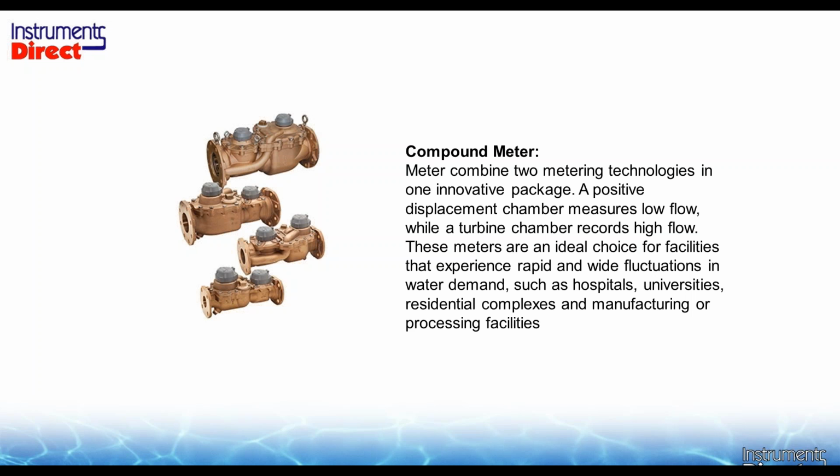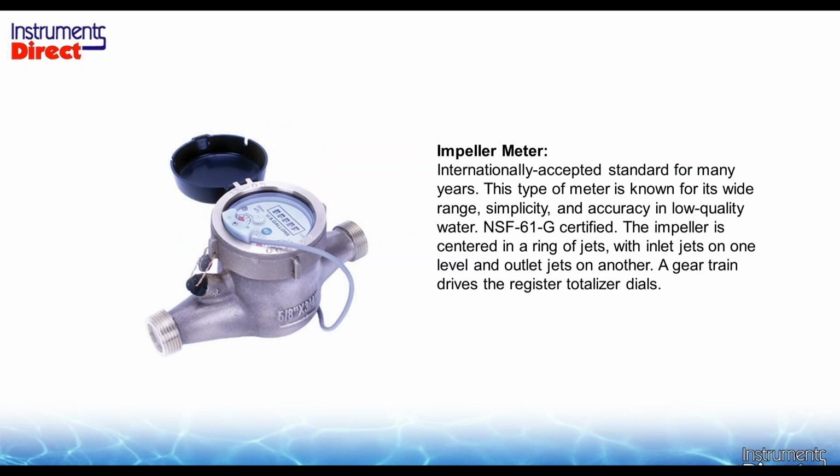So if you wanted to monitor a big water line, know your minimum flow rates before you go in and get yourself into trouble. Now, the other types of meters, and I said there's just a plethora of meters. We're just going to go through some conventional technologies here to get you oriented. So again, on the water meter side, something that you're going to use for a drinking water application, make sure that it's NSF certified.